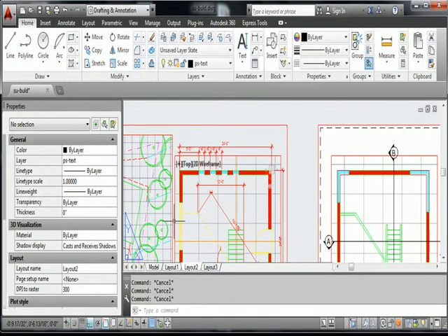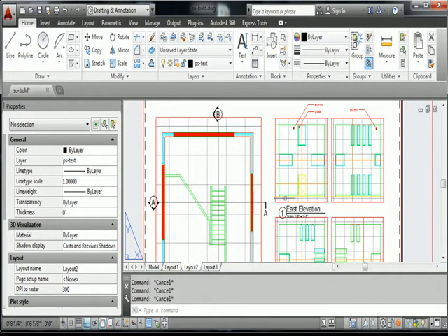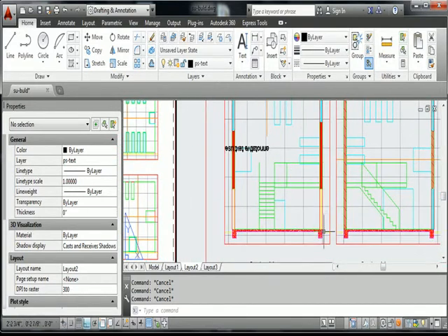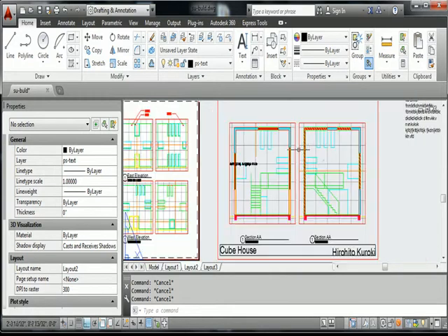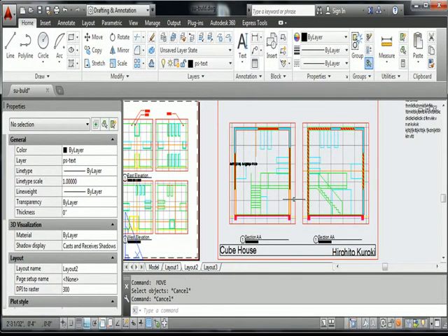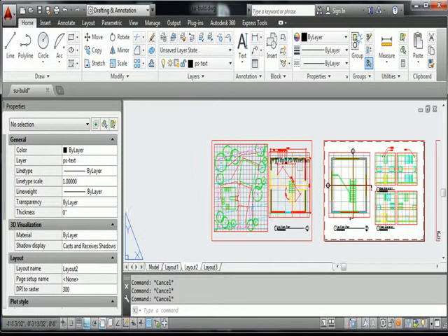We're going to do this all around for the first floor and for the second floor, and then just the height for the elevation. And for the section, you will need to indicate a dimension height from the floor to the mezzanine, and then from the floor to the roof. So that means that these drawings might have to spread or move apart a little bit as well. Okay, so when we're all said and done, we should have a nice labeled, finished looking plan.